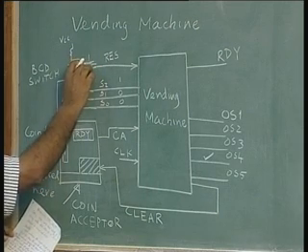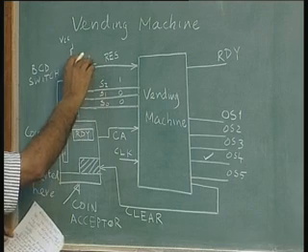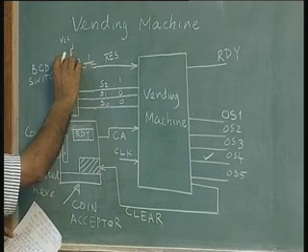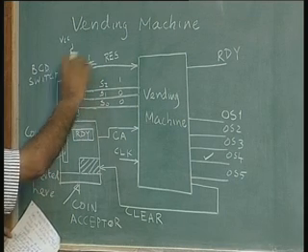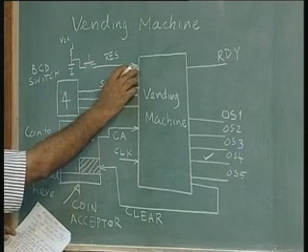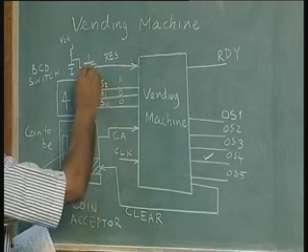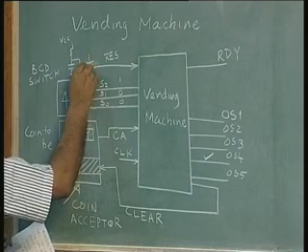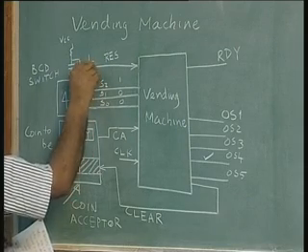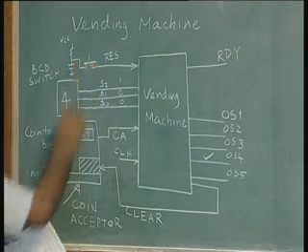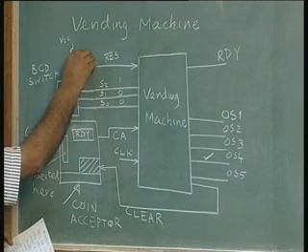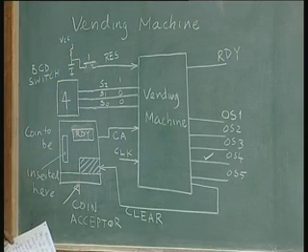When you close the switch, the capacitor voltage, 5 volts, is applied to this reset position and stays on for a while, and that is the indication for the reset. So, this is a normal procedure they adopt in many circuits for power on reset, they call it. So, this is how you push the button to get the reset signal.